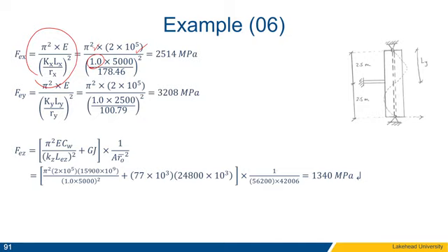One thing I will probably need to emphasize is the buckling length. We will find that the buckling length in the x-axis will be the full length. We discussed this earlier. While the buckling length in the y-axis will be half of the length due to the beam in the middle.